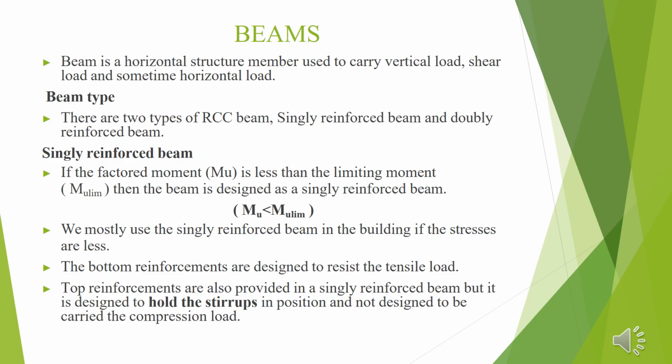We are not going for singly reinforced beams, because this gives reinforcement only at the bottom part, which is not very good in practical cases. So if your stresses are too low, or if you are going for load bearing structures, singly reinforced beams can be used. The bottom reinforcement is designed to resist the tensile load. So for tensile load, bottom reinforcement is given, and for the top compression zone, no reinforcement is given.